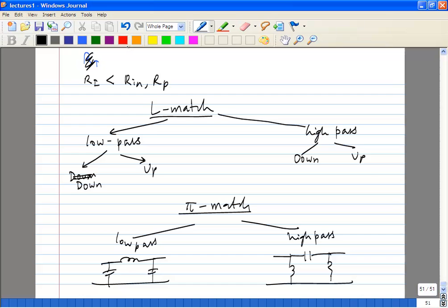Okay, so yeah. In this case, L1 plus L2 would be less than L also. Yes, but the difference is, here you have L, so you have C1, C2, and here L1, L2, C. The difference is here you have a single inductor. Remember that Ri, the intermediate impedance, is actually a fictitious impedance. In the real lumped network, you're not going to create L1, L2 separately. You're just going to design a single L. Whereas here you need two physical inductors. Two physical inductors are always much bigger than just creating one larger inductor.